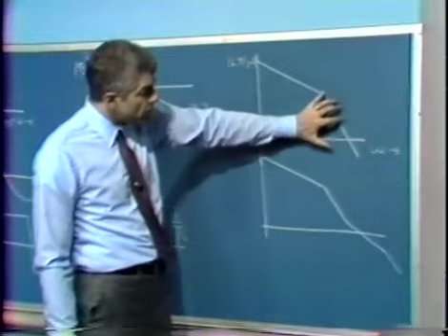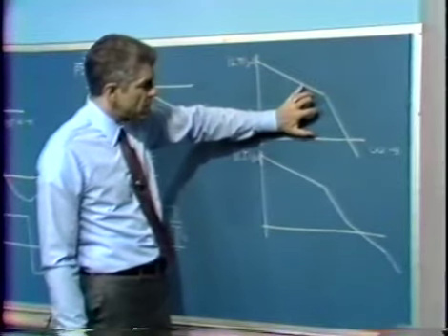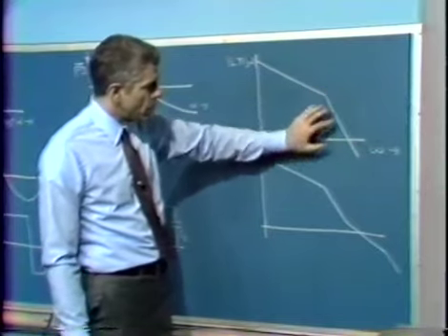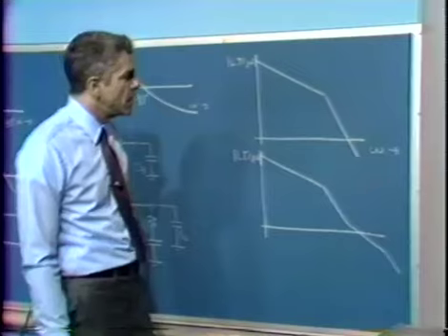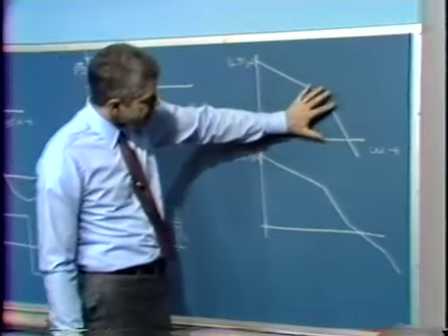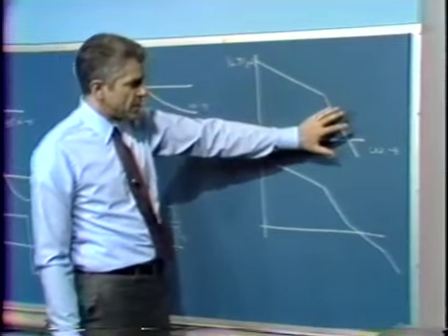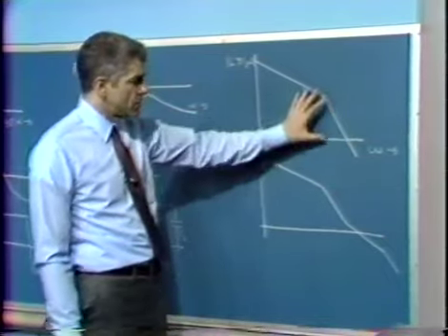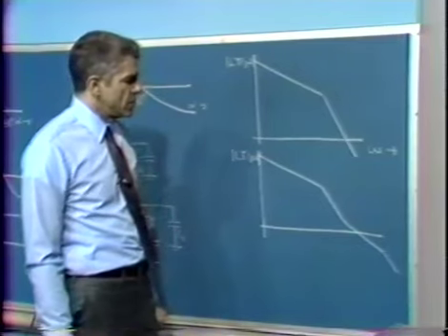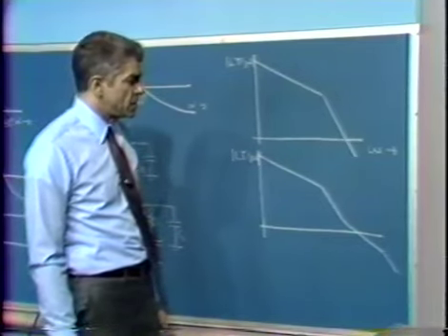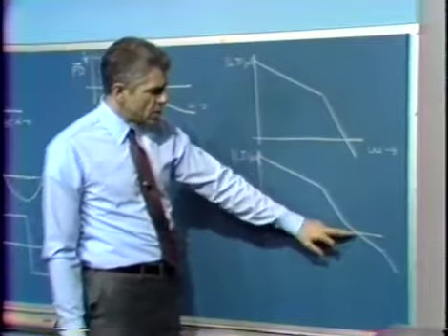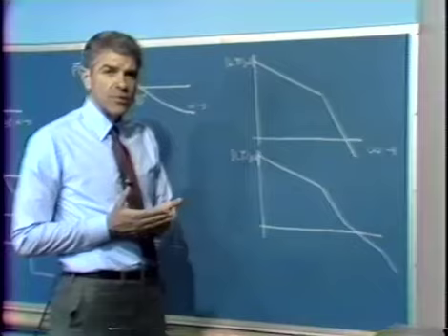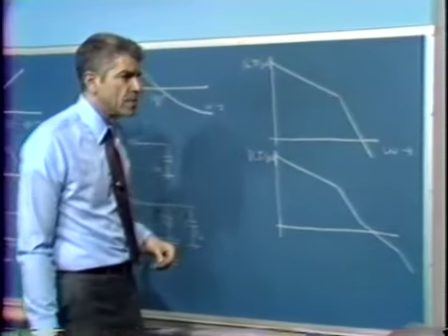And if we did this, if we pushed the pole back to very low frequencies, we'd have poorly stable performance. We'd have low phase margin in the system. We could, of course, use a smaller value capacitor, one that was adequate for filtering the ripple out of the phase detector, but didn't create this problem. However, there's an alternative that can be used to give us somewhat higher desensitivity, given that the crossover frequency is more or less a fixed quantity because we have to cross over at a small fraction of the operating frequency.